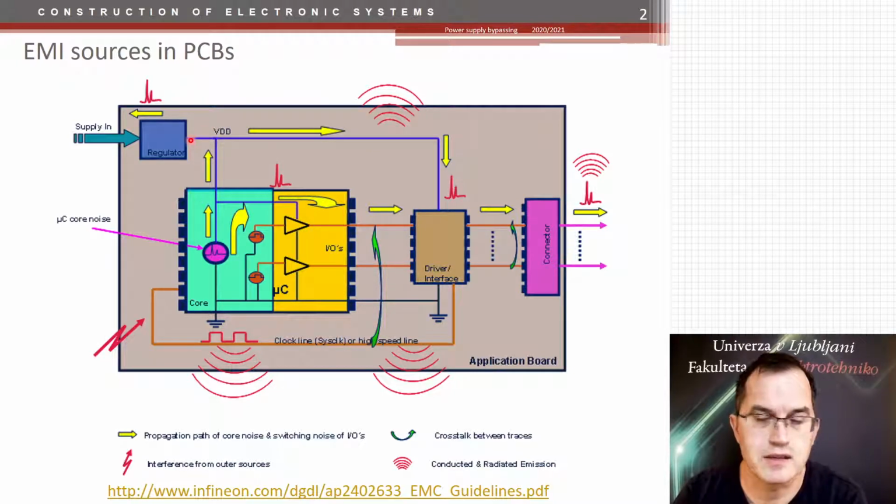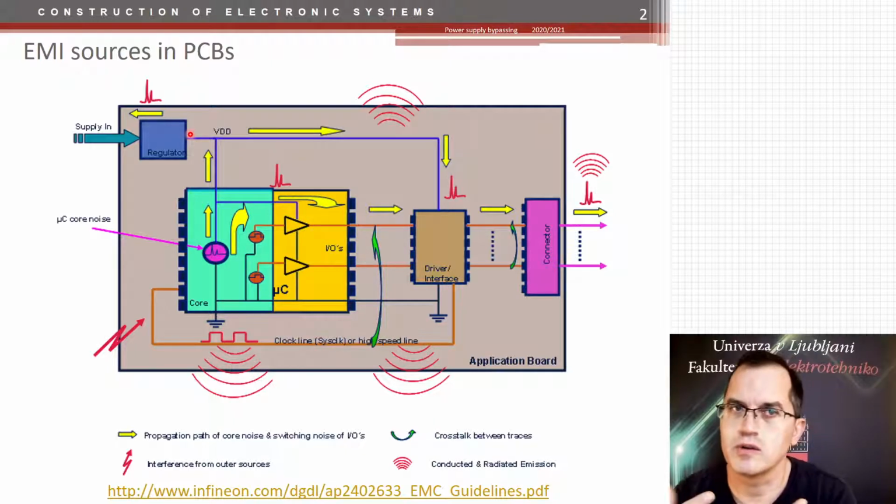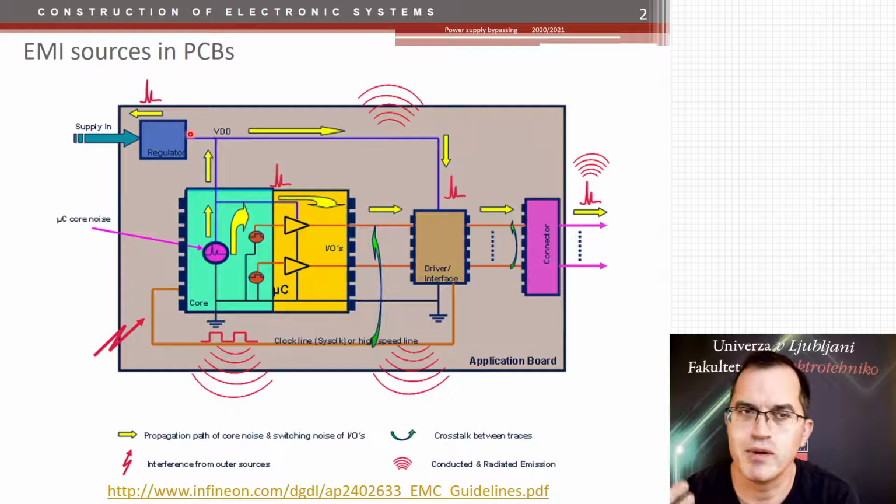of electromagnetic interference. And although these power supply lines do carry DC voltage and DC current, they also carry a lot of noisy current that comes as a consequence of the high-speed circuits that are supplied. And this noisy current is then transferred through the power supply lines via so-called common resistance paths.